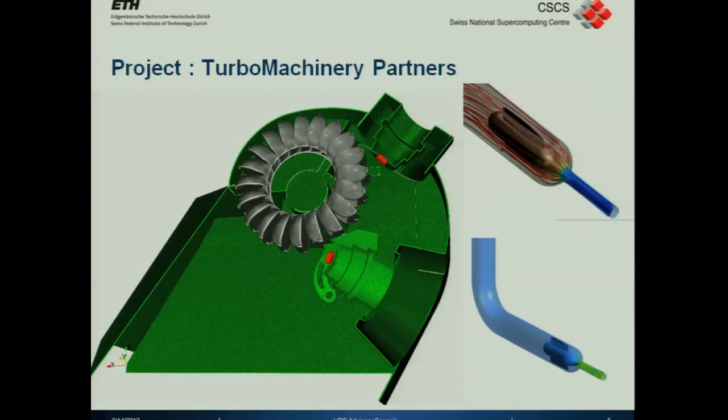And these wheels are actually usually mounted in a horizontal frame of reference, so they spin like this rather than like a wheel. And what happens is the water splashes out, and this casing is all basically sealed. They can have as many as 6 jets all around here, and if the water comes out there, splashes, and then lands on another jet, it disturbs the flow, which in turn causes the jets to spray out, which means you lose momentum.